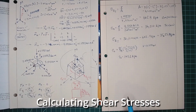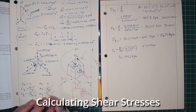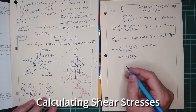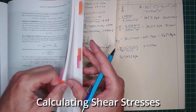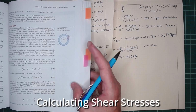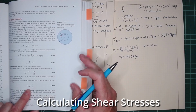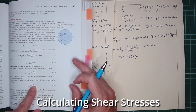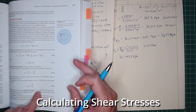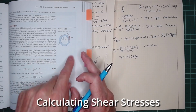So we're left with just one more to calculate, and that is our shear stress due to our torque. In this case, we need to go all the way back to chapter 3. If we take a look at our equations here, our tau max is going to be equal to T, our torque, times our distance to our point, over IP. For a circular cross section, we can look that up in the back of the book.